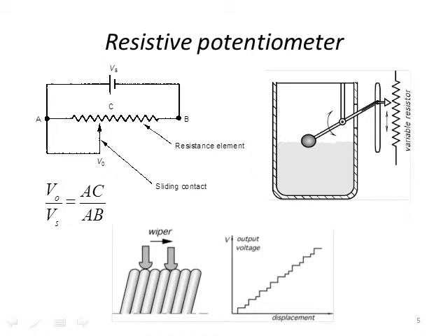This is an example of a resistive potentiometer. Very, very simple. Essentially, the wiper arm of the potentiometer is connected to a moving entity. In this case, a water level is pushing up on a rod and forcing a torque and moving the wiper of the potentiometer in a particular direction in the upper right-hand picture.